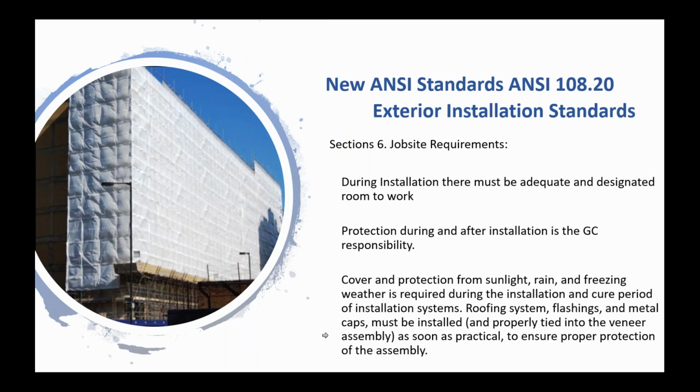When you're doing gauge porcelain tile, stop and talk to the GC and say, look, I need to have this protected from the top as I'm doing the installation and as quickly as possible afterwards, so we don't fill that wall up with rain. I'm not so worried about the rain creating bonding issues so much as it coming out and leaching out through the tile and the grout joints later, and possibly leaching latex.